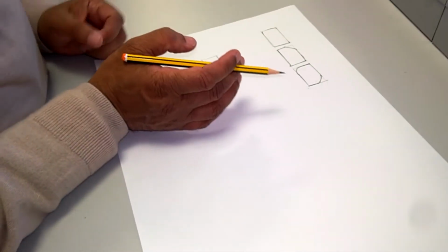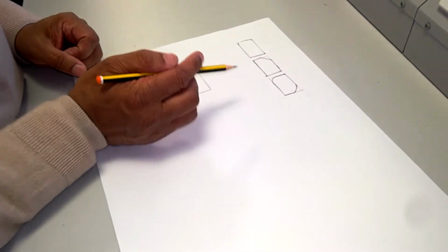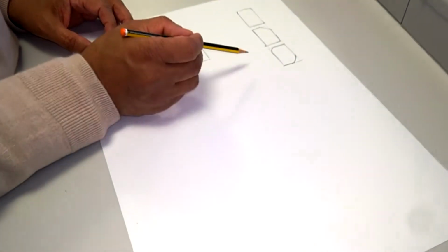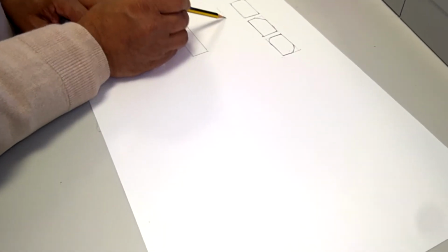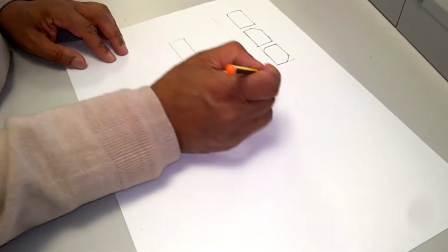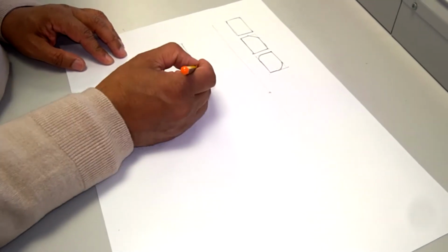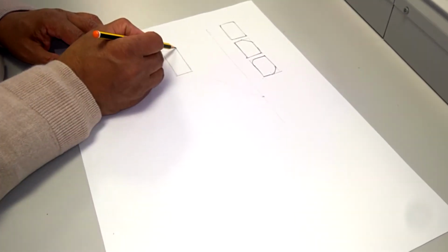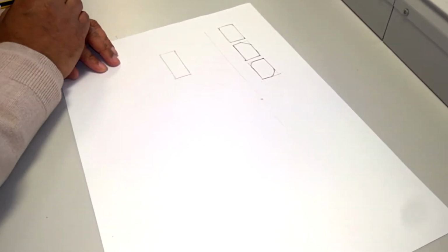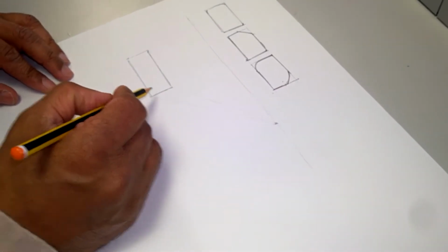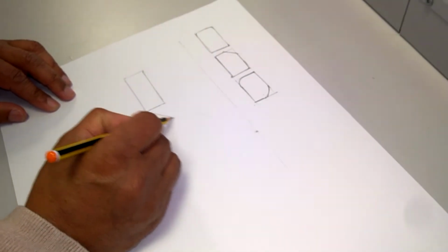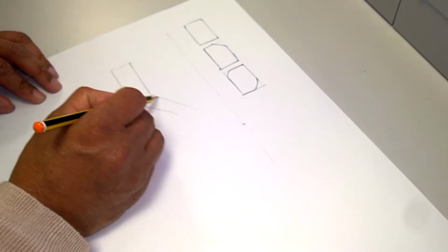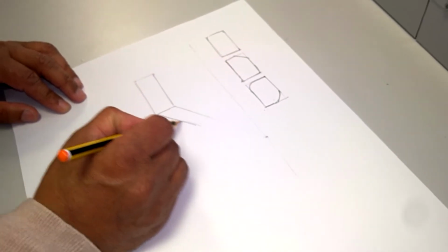When you've got this, there's two ways to add to this. One, if you're doing the 1 point perspective, put a line there, put your vanishing point, and just take those to the vanishing point. Or if you're going to do 45 degrees, you can still do a similar sort of thing. Do them parallel this time, same angle. You get extra marks.